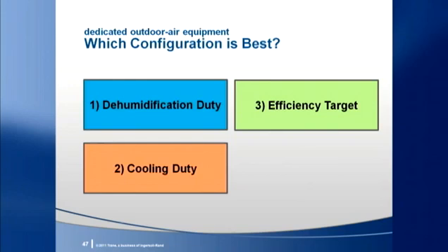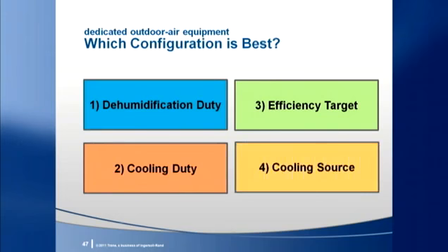Third, what's the efficiency target? Does this system just need to meet the minimum energy code, or do you want it to be more efficient? And finally, what's the source of cooling energy? Where will the heat be rejected, and what is available, and what could be available?